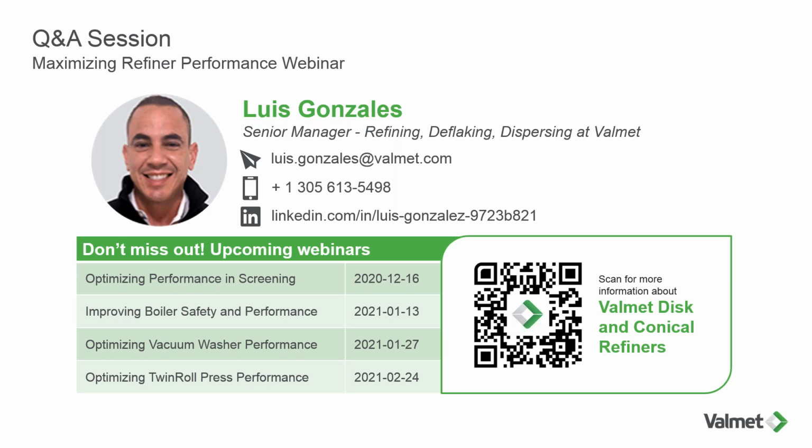And again, obviously, the process is the second factor. It's the biggest factor. It's the only lubrication point. So if you're using some white waters in which, for instance, to throw out a random example, some cement applications and the white water has bits of cement in there, or some contaminants with high abrasiveness going through the system, and this is what you're using as your dilution water, then that is also going to impact refiner spline life. I hope that answers that question.